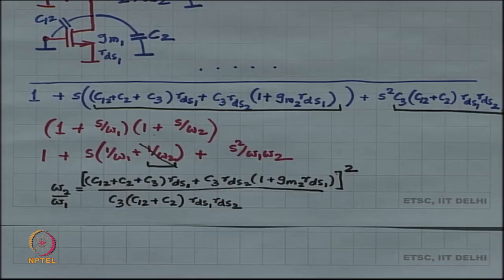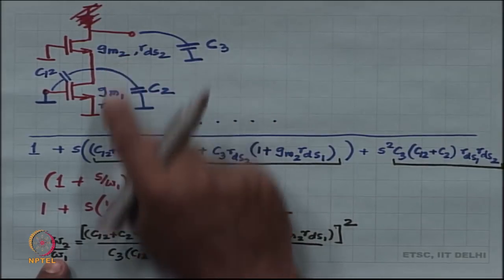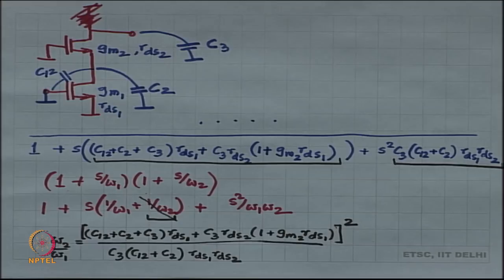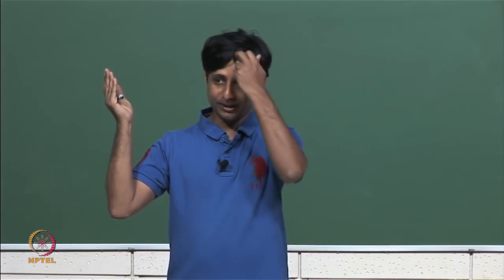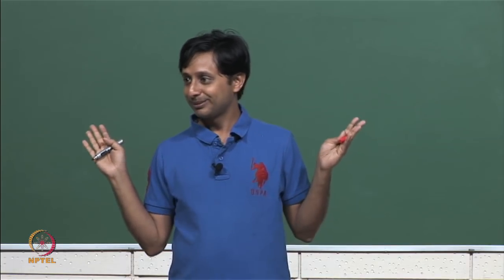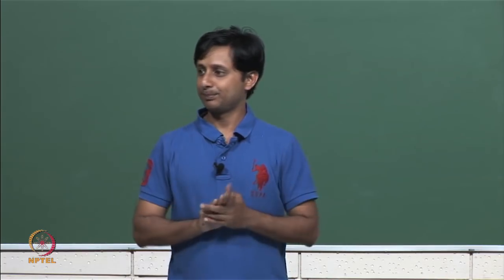Now, this ratio has to be set to a certain predetermined constant, a large number. How will you do the engineering over here? What will you tweak that will get you the maximum benefit? Which one of these will you tweak to get the maximum mileage? If you look at it carefully, first of all, you are not allowed to tweak the values of gm1, gm2, Rds1, Rds2, because this is what gives you the DC gain. Okay, the DC gain is all important. If you change the DC gain, then guess what, your set value is no longer set, right, that also changes, right, that is a function of A naught, that set value. So, you can't now tamper with the DC gain, the DC gain is fixed, right, that means gm1, gm2, Rds1, Rds2 you are not going to touch.